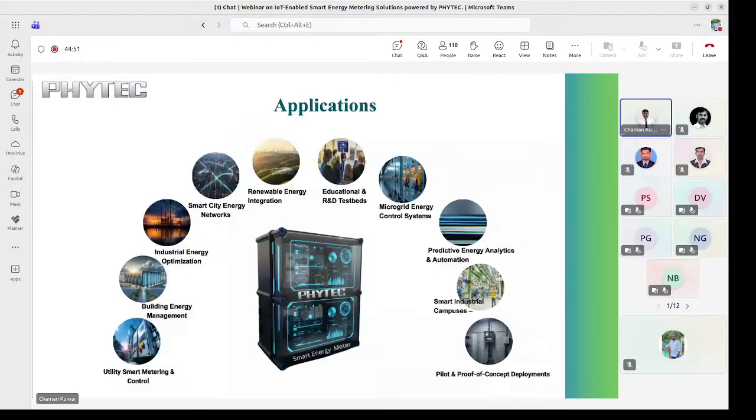So here we can directly read from RS485, we can read from optical meter reader. If I want to go for RF mesh, wirelessly reading the data from the meter, at that time I will go with TCP/IP and the NIC card, network interface card, and if it is cellular, I will go for the GPRS modem. If you want to read the data through power line communication, which is wired, then we will go for the PLC header. We have a PLC modem. So this is how the DLMS COSEM architecture framework works.